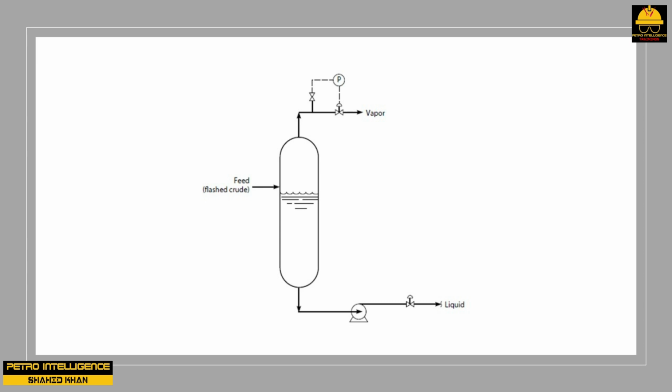If he raises the pressure in the drum suddenly by 5 psi, this instantly supplies about 20 feet of additional available NPSH, but only for a period of less than 10 minutes. During this period, he can crack open the pump discharge valve, push the motor start button, and then slowly accelerate the liquid in the suction line by slowly opening the discharge valve. If he can do all this before the lighter liquid formed at the vapor-liquid interface in the drum reaches the eye of the pump's impeller, then he can start up the pump. Thus, even though we lack the extra available NPSH to satisfy the pump's starting NPSH requirement, he could still start the pump.